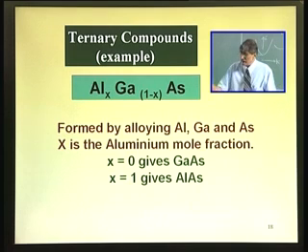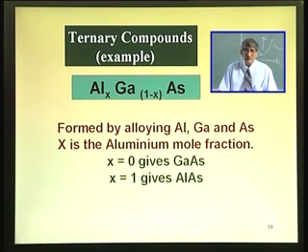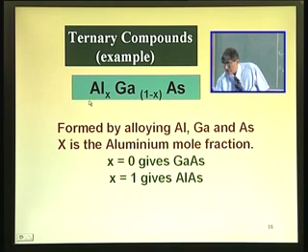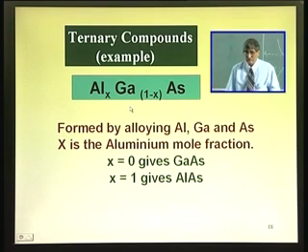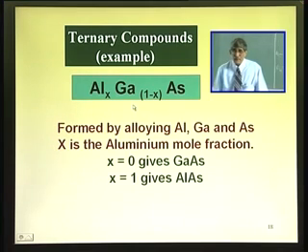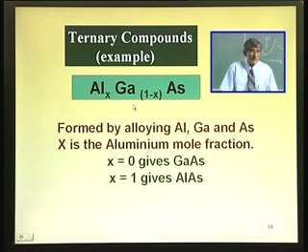Now, aluminum gallium arsenide, AlGaAs, if there are 100 arsenic atoms and 50 gallium atoms and 50 aluminum atoms, x equals half. If x is half, 100 arsenic here, 50 here, 50 here. So, that is the meaning of x, the mole fraction. Stoichiometry is maintained. The total number of arsenic atoms is equal to the total of aluminum and gallium. What is happening is, where gallium is supposed to be sitting, the aluminum is sitting there. It is faking for gallium.